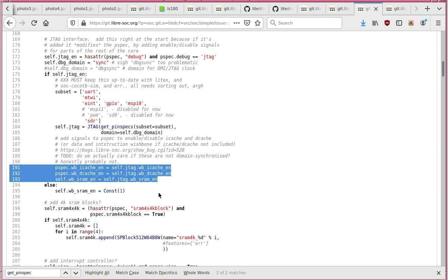But a tri-stated big resistor, but we decided not to do that because it would complicate the power provision to the chip. So we only have 2 rings, a 3.3 volt ring for I/O and a 1.8 ring for the main core.